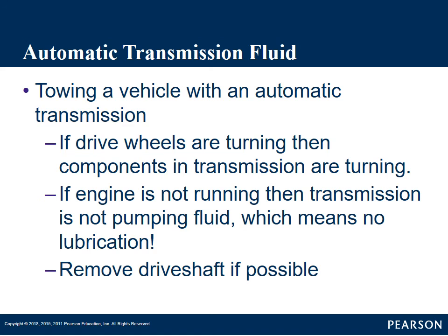Our next little bit in this lesson is towing an automatic transmission. If the drive wheels are turning on that vehicle, components in that transmission are turning. But if the engine is not running, the transmission pump is not pumping fluid through that transmission, which means you're not getting any lubrication.